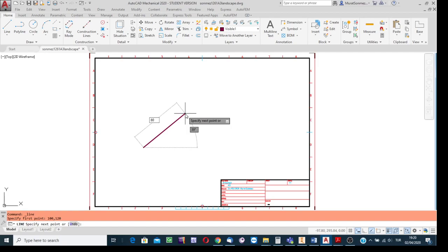And then there is a trick at this stage to know. If you're going to input this number as the length of the line, and then the other number as the inclination angle, this is a must: click on the Tab key of the keyboard. Which key is the Tab key? On the computer keyboard, you can find the Tab key, on which there are two arrows, one directed to the right, the other directed to the left. Click on the Tab key. Don't forget this.